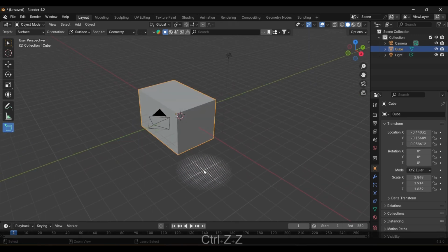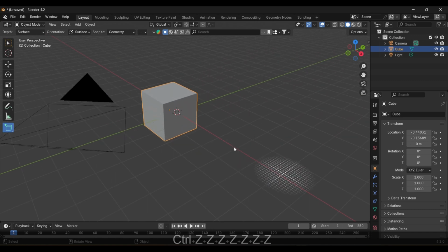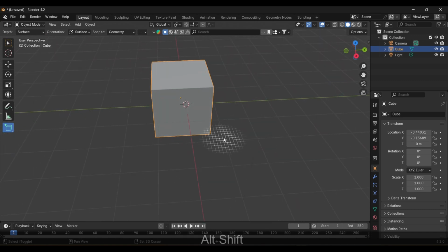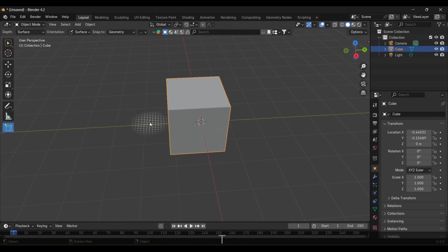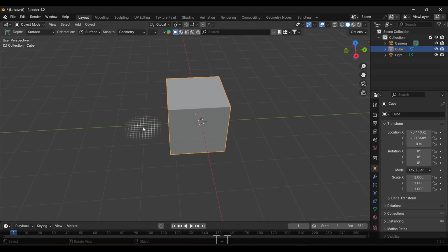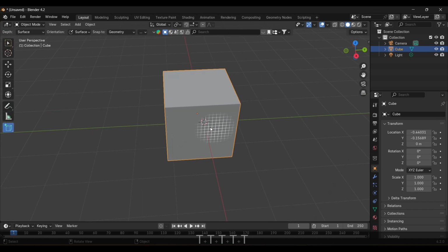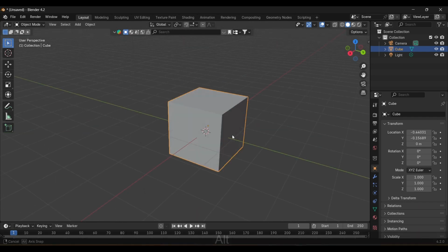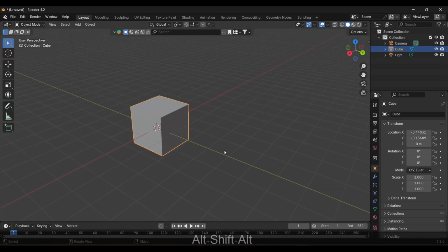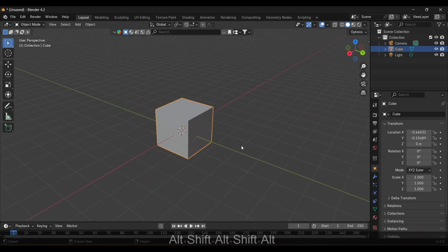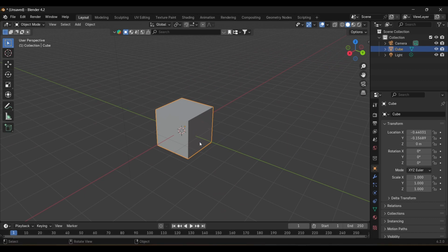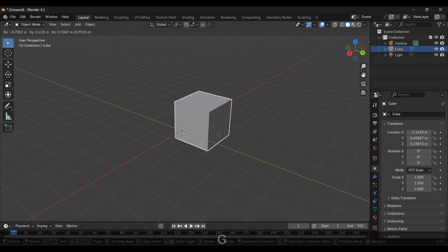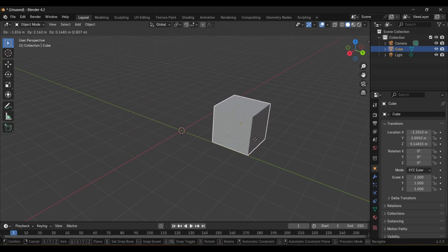These are not used so much. We will use shortcuts, and we are not going to use this tool. We can hide and unhide by pressing T on your keyboard. Now again select this selection mode, and I'm going to explain some basic shortcuts. For movement, press G on your keyboard. We can move anywhere by pressing G.